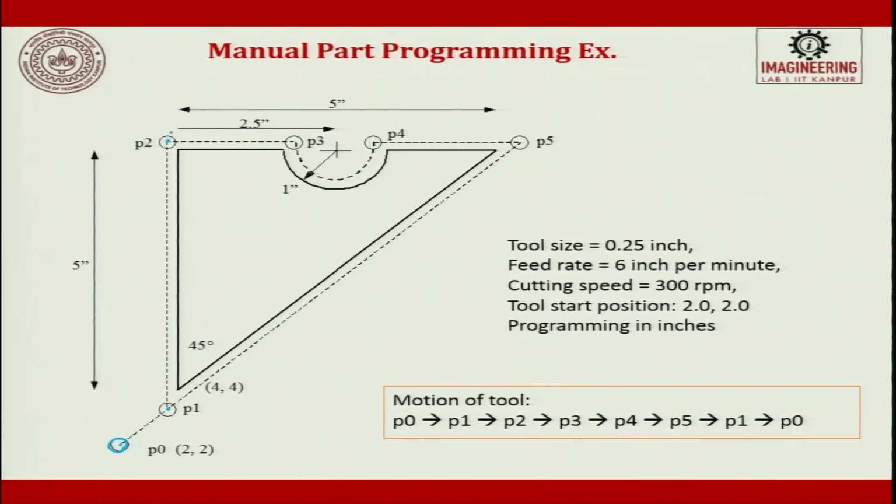You know the length, you know the angle, which is set at 45 degrees. Then from here you come to the offset, then you have a radius. The radius is divided into 2. This is one clockwise; if you take it as counterclockwise, then this becomes your clockwise, whatever it is. You can go up to here and then split, or you can use the same command and swing it up to here. P4. So, this will be G00, this will be G01, this will be G01, this will be either G02 or 3 depending upon your requirement, and then this is G01 and then G01.